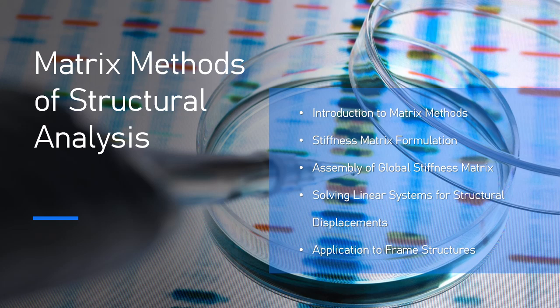The two most common iterative methods are 1. Conjugate gradient method. The conjugate gradient, CG, method is one of the most widely used iterative methods for solving systems of linear equations where the stiffness matrix K is symmetric and positive definite, which is typically the case for structural problems. The basic steps of the conjugate gradient method.